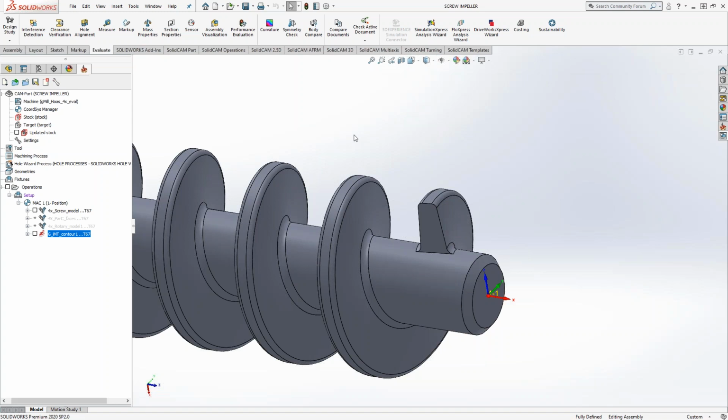And the name, like Brian said, is a little bit of a misnomer. It doesn't mean you need a Swiss screw machine to do it. It just applies to screw type geometry. But even then, you can do it on, let's say, that part we were looking at previously. It doesn't have to have a screw shape to it. It just means it's going to generate a helical toolpath. Rather than call it something like helical machining, which throws us for a loop as well, it's basically screw, like a helix around a core. But we'll leave it there because we're a little over time, and we can easily do this tomorrow. We'll go in more depth.